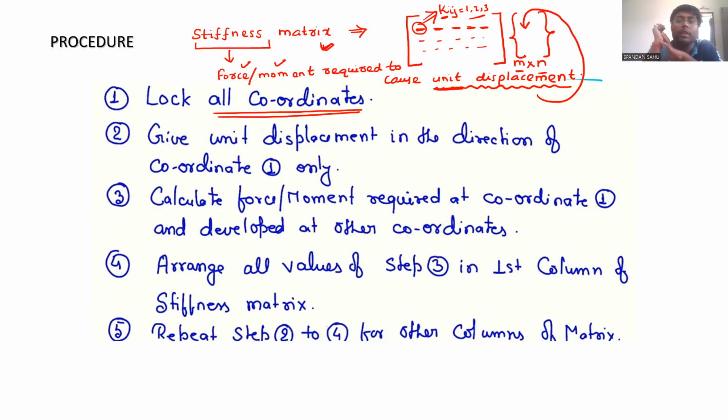When we are reading force method, we are removing all those redundants and we are applying unit load one at a time. Means if the DSI of the structure is greater than one, then we are removing all those redundant forces. We are allowing the external load to apply to that structure, which is statically determinate as well as stable, due to which we are calculating all those deflections or displacement depending upon the problem.